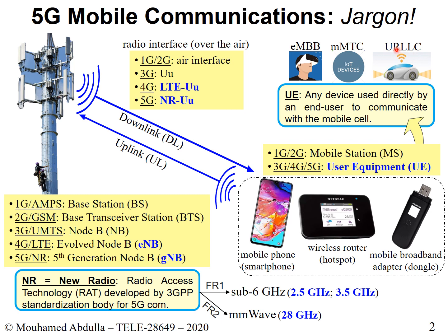As for URLLC, this stands for Ultra Reliable Low Latency Communication. Essentially this is when you require high reliability, somewhere around 10 to the minus 5 and perhaps even higher than that. It could range up to 10 to the minus 9, depending on the automation level. If we're talking about level 2, level 3 automation, 10 to the minus 5 makes sense, but in more advanced automation you'll need much higher performance. It also refers to low latency, somewhere around 1 millisecond to 5 milliseconds.